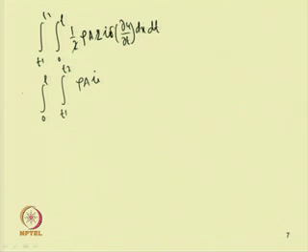here we have this del term. So, u dot, and one can interchange between this del by del t and del u. So, one can write it this way, into dt and dx. So, this equation can be written in this form, rho A u dot, then changing between del and del by del t, one can write del by del t of del u dt. Now, one can use integration by parts.